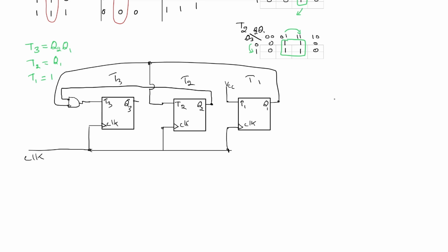On each clock edge, each flip-flop will store 1 bit. When we start at 0, 0, 0, nothing is detected. If we have one clock edge that is detected, this will be 0, 0, 1. So 1 will be stored in one of the flip-flops. On the next clock edge it will be at 0, 1, 0, and so forth. And when we get to 7, it'll start over.